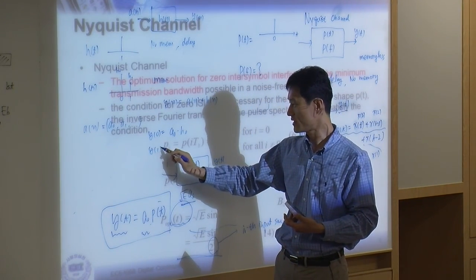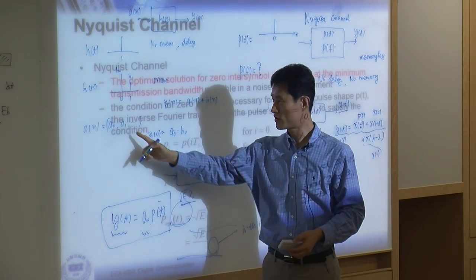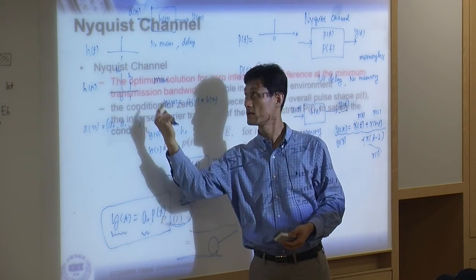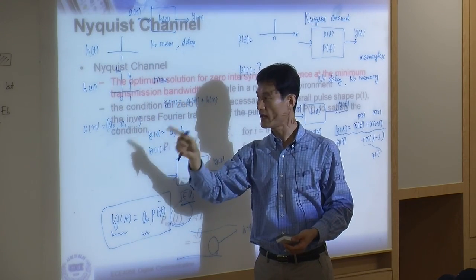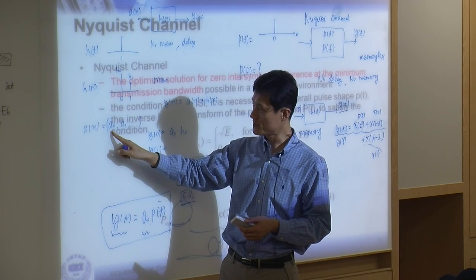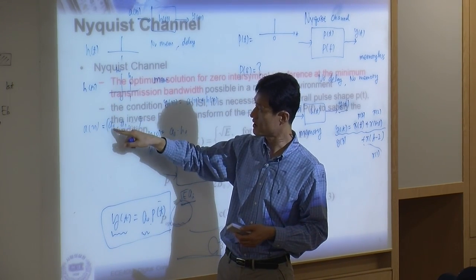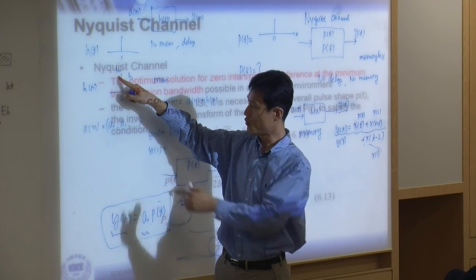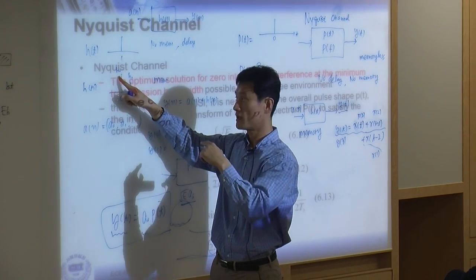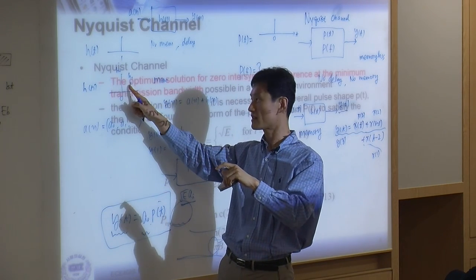What is going to be your second output? Now at the second output, your second input, a1, comes in. Let's go back. The first input sample comes in and is multiplied with h0. When the second input comes in, the first input stays in the memory and moves to the next.